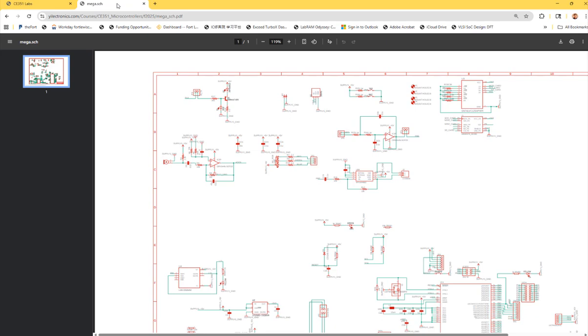The similar effect happens if you put it in a box, or if you just randomly place your IR light in front of a darker surface, then it won't get a lot of reflected signal, and eventually you are not receiving anything. If you couldn't solve that problem, the easier way is to place a white paper in front of the emitter, so you can receive a way more reliable signal. If you see some error messages, just put a paper in front of it, and it will probably fix it. Okay, and that's one thing.